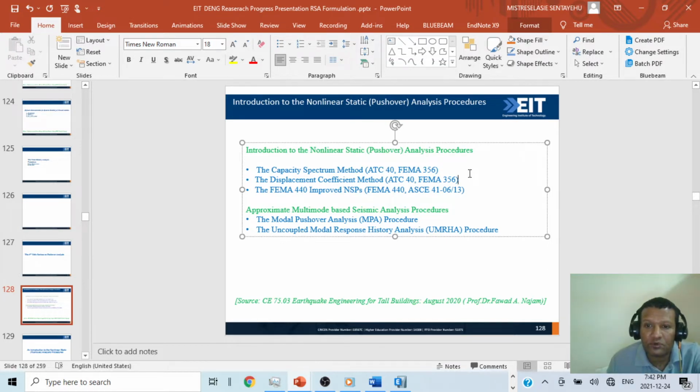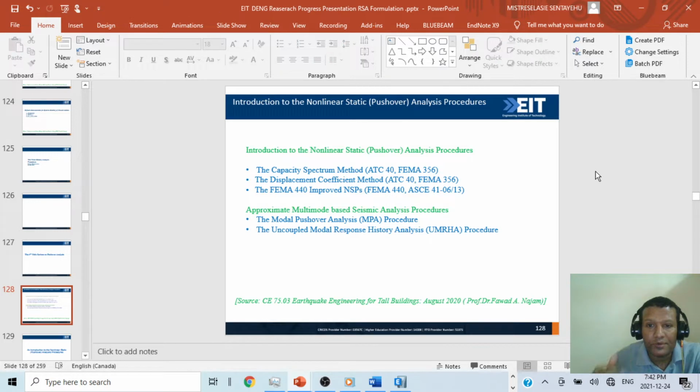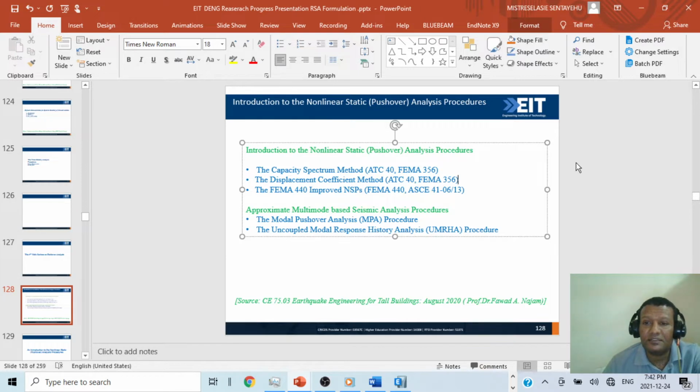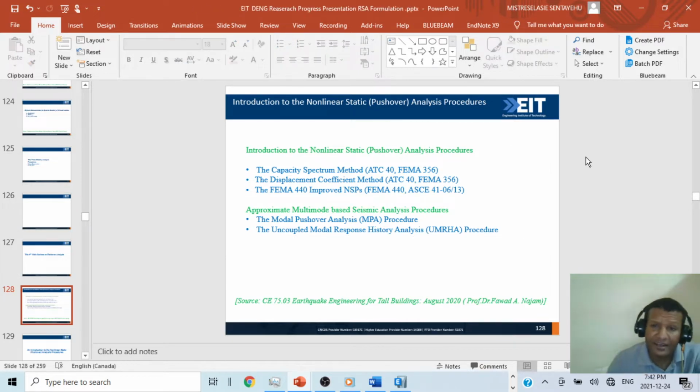Once we know these performance points, then, as per our nonlinear model, we will assign our force deformation curves and the hysteresis rules together for that capacity. That is the idea of performance based. But to know what the target displacement is, that is the problem. So we will discuss how we are going to find this target displacement.